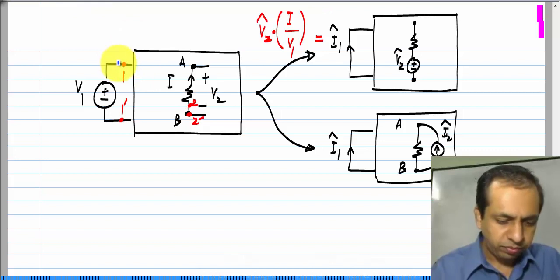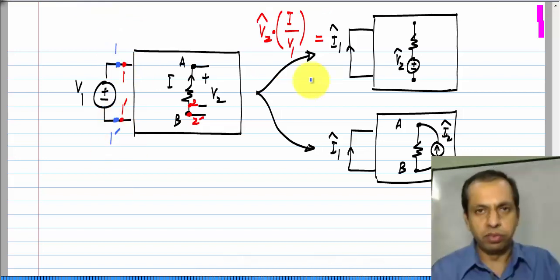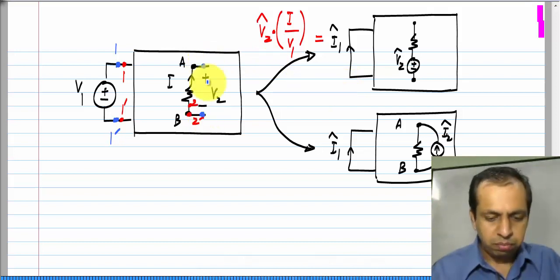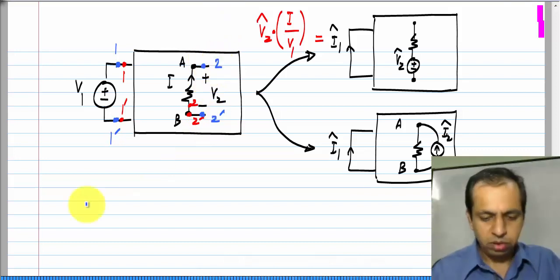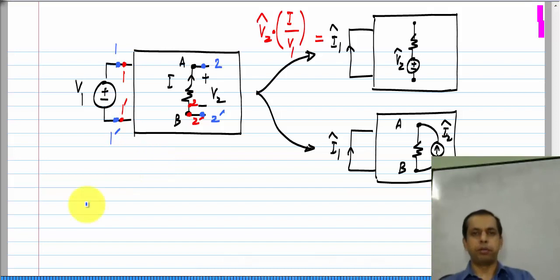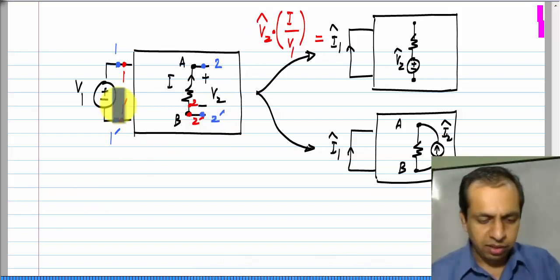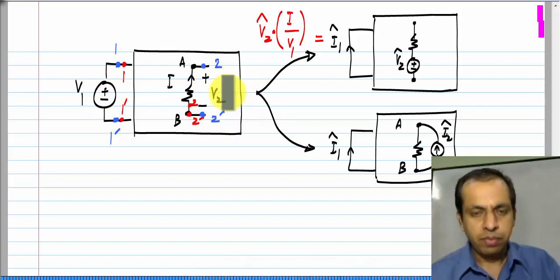Similarly, in this case I can relate this case to the original case by defining something else as the 2 ports. So, let me call this port 1, which is the same as before, and now between node A and B I define the second port, port 2. Okay. So, now if you do that, we can see that basically this V2 by V1 is nothing but G21. Okay.